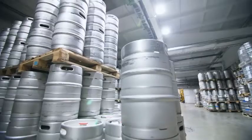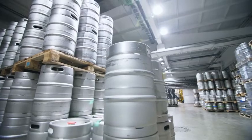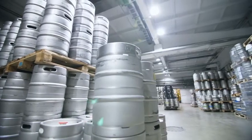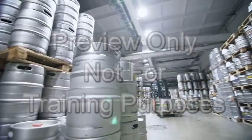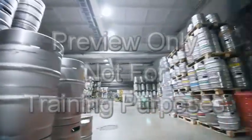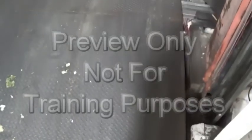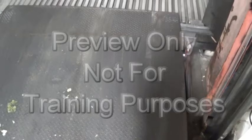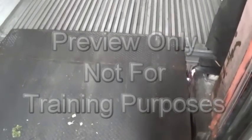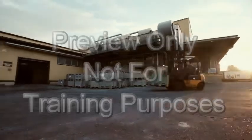Workplace conditions. Operating a forklift safely also requires awareness of the workplace and the conditions under which you are driving. You must be aware of things such as physical conditions, pedestrian traffic, and loading docks, just to name a few items. All operating surfaces must be strong enough to support the forklift, the operator, and the load. Surfaces should be free of holes, grease, oil, or obstructions.